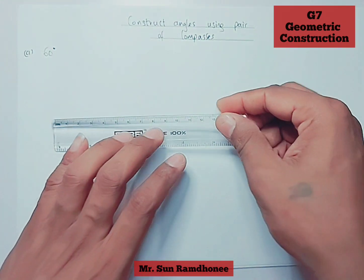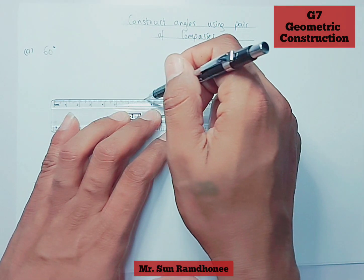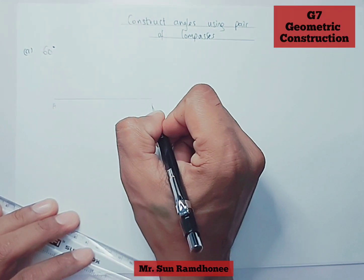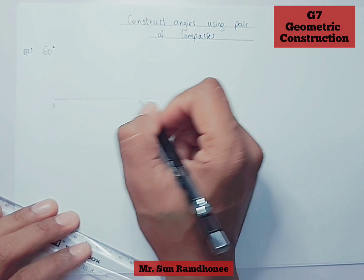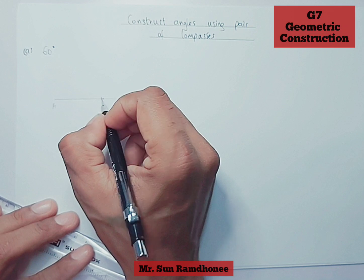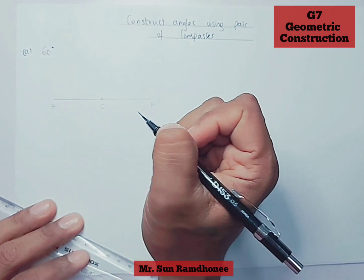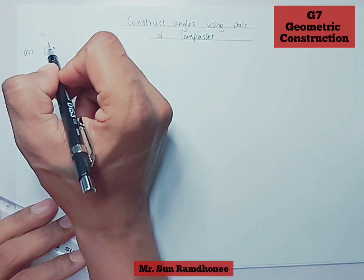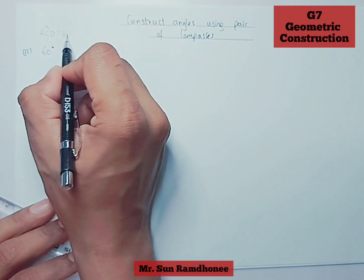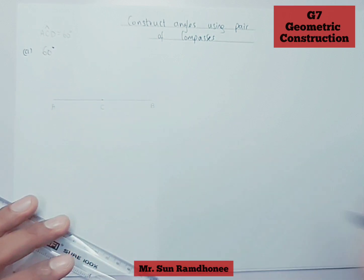First of all, what you have to do is that you have to draw a horizontal line, and then we are going to label it A and B. We are going to choose a point approximately in the middle, and we are going to label it C, which would mean that angle ACD is equal to 60 degrees. The 60 degrees angle will be at C.